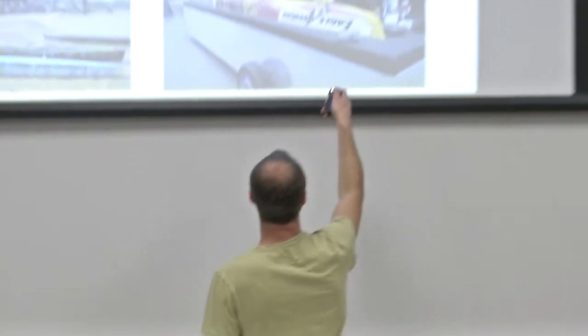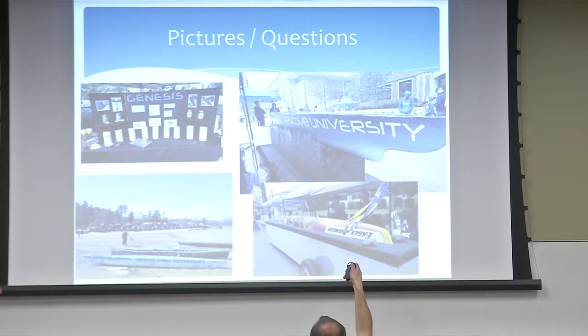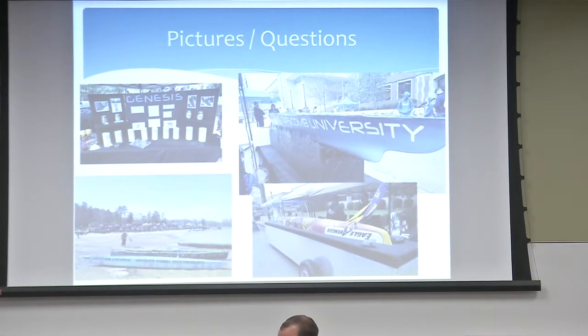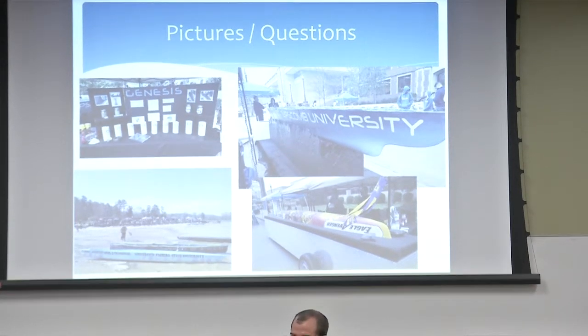Our canoe, we had to apply more styrofoam in the inside in order for our canoe to come back up. So yes, the goal is to make the canoe fully out of concrete. You can't tell from this picture, but we actually placed end caps that had styrofoam inside the canoe that we encased over with concrete, and that is legal. You're allowed to do that, and there's no deductions involved. But once we failed our first swamp test, we had to apply more styrofoam in order for it to float, and we got a little deduction because of that.